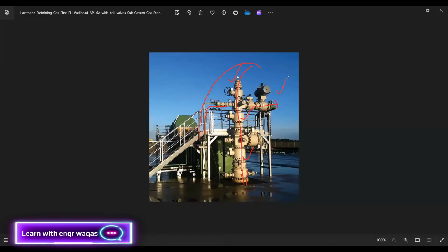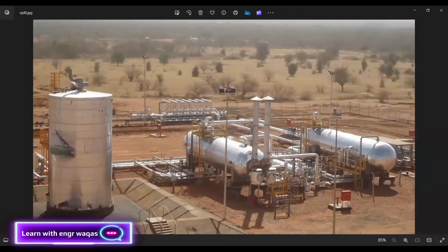This wellhead is going to attach to such an assembly. See over here, these production lines involve different kinds of equipment. But if I look at this picture, I can see that there is civil work involved. This is a foundation, and there will be earthwork. This area is the same as this one. See, there are herbs, shrubs, and trees, not a regular area for placement of these vessels. So we need leveling, earthwork, sub base, aggregate base, compaction, and foundation concrete work. A lot of civil work is involved.